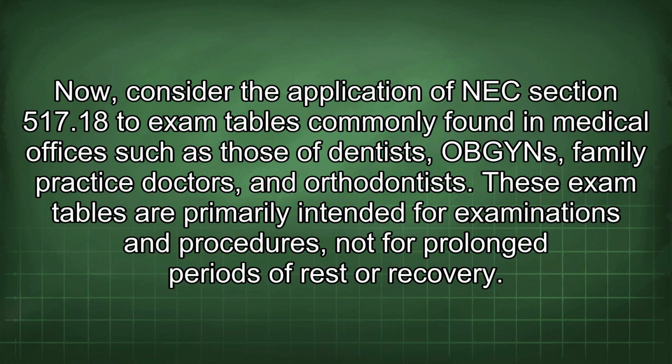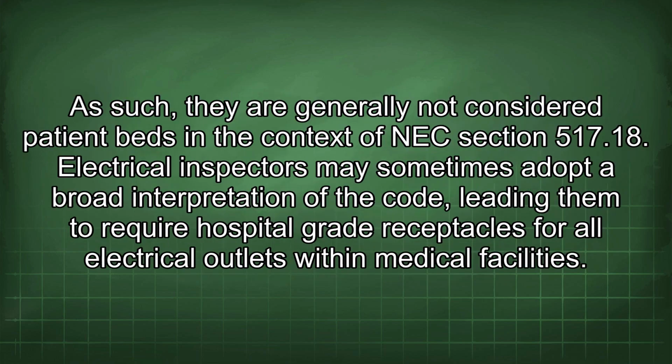Now consider the application of NEC section 517.18 to exam tables commonly found in medical offices such as those of dentists, obstetricians, family practice doctors, and orthodontists. These exam tables are primarily intended for examinations and procedures, not for prolonged periods of rest or recovery. As such, they are generally not considered patient beds in the context of NEC section 517.18.